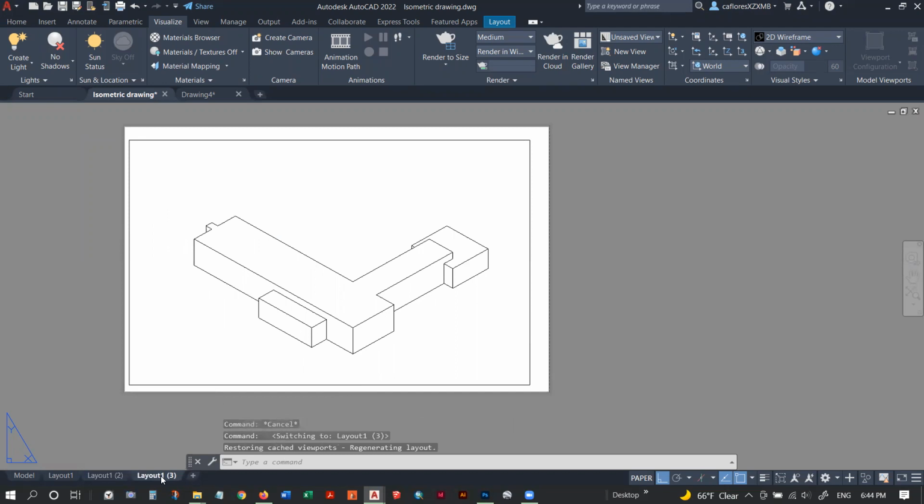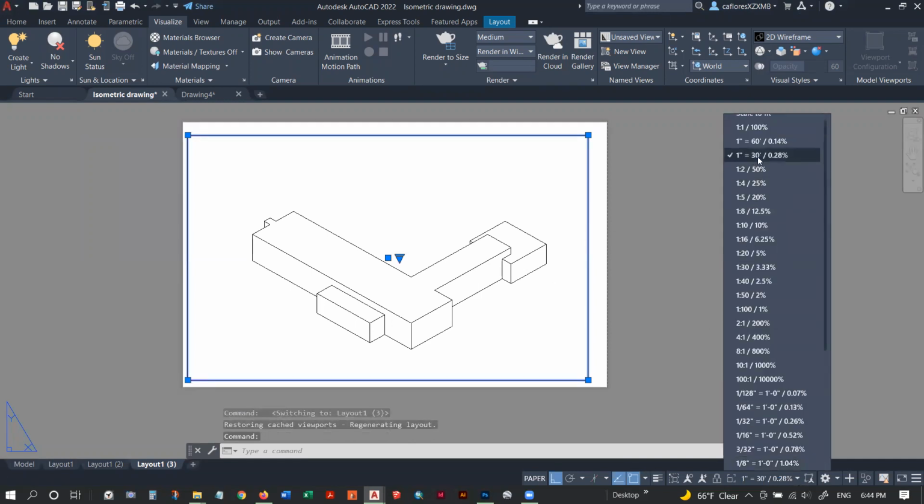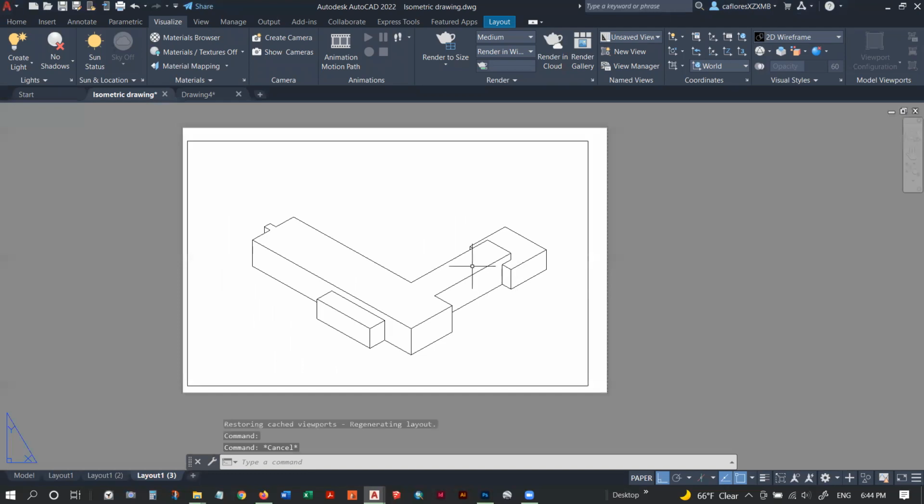However, in this new drawing that I made in this tutorial, the 3D model, even if I choose the same scale, 1 inch equals 30, this is now an actual isometric view of the model. It's not that fake isometric drafting that I did before where I used the actual measurements. This one has the actual measurements, but it is now seen in isometric projection, actual isometric projection, which causes foreshortening.